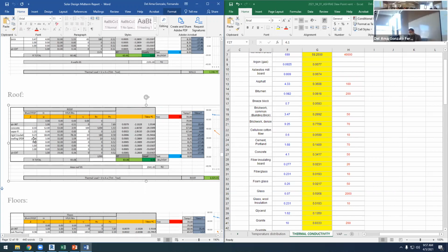Ah, okay, so you took this from Revit. Yeah. And the vapor resistivity from Revit as well? I don't remember where I got that from. Okay, great, but you took this from Revit. Yes, we have to be resourceful. If we don't find this material here and we have this material in Revit, let's do it. So the EPDM thermal conductivity is 0.96.